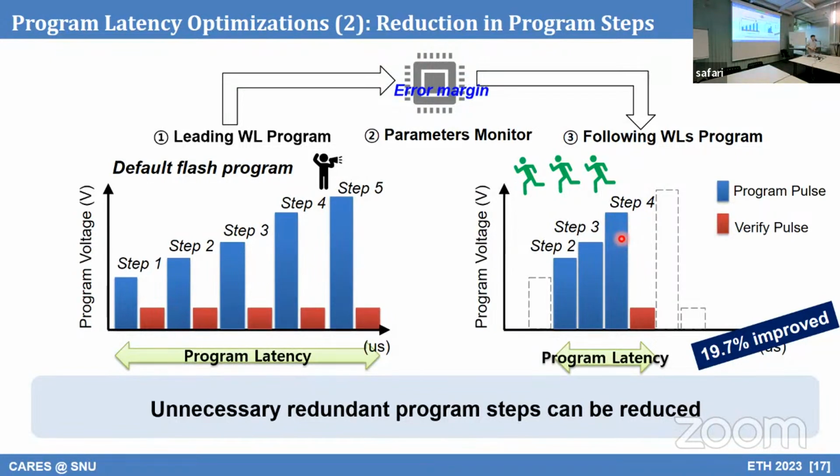Yeah, good question. There is also one question on YouTube: why is this optimization not exploitable in 2D flash? In 2D, you don't have a horizontal similarity, because the similarity of the horizontal layer mainly comes from manufacturing characteristics. So in 2D it doesn't exist.